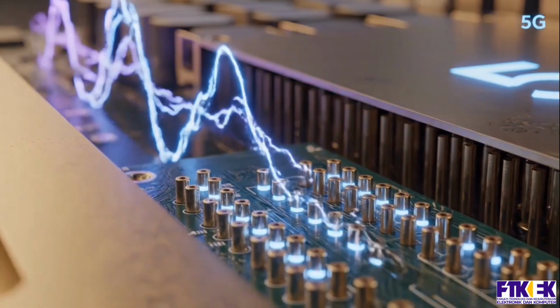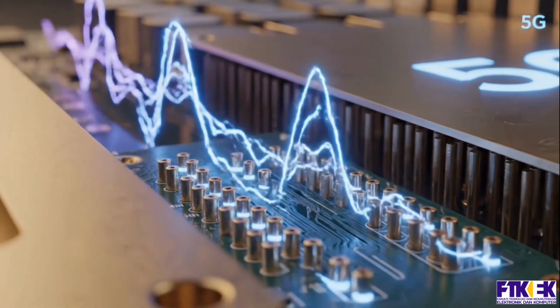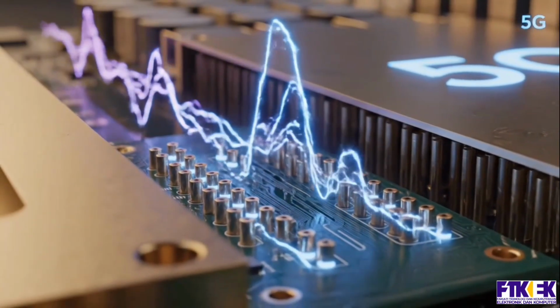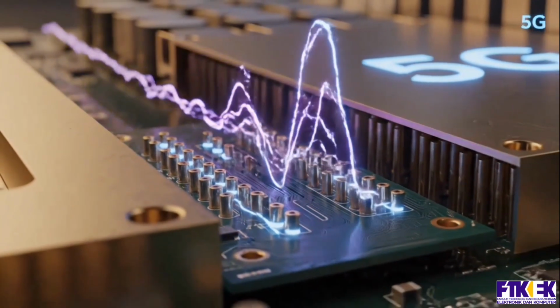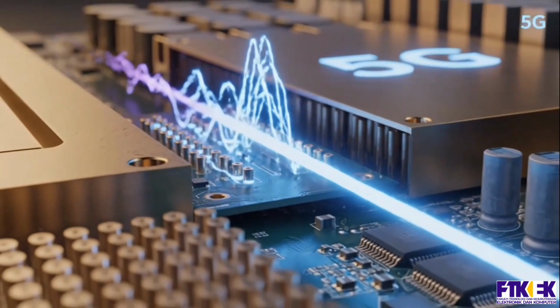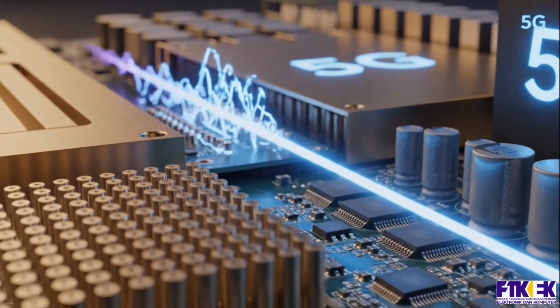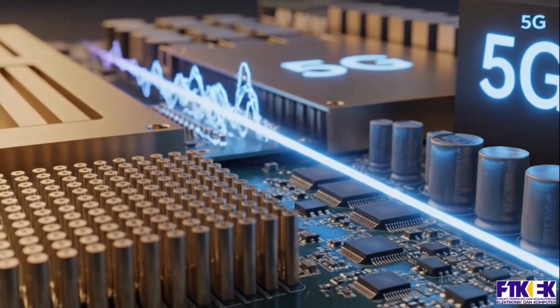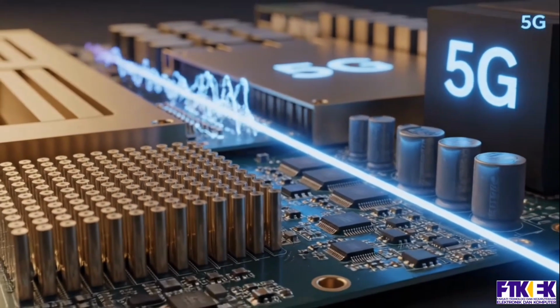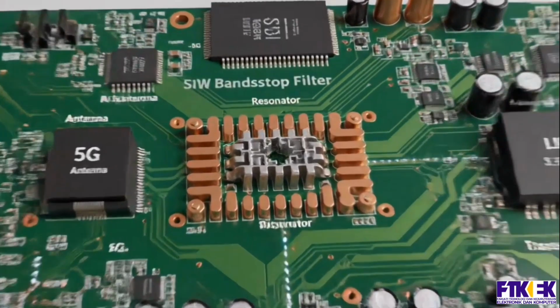Our design criteria were strict. The filter had to be compact, low profile and highly selective. We achieved a total length of 95.33 mm and kept the reflection levels below -15 dB to ensure maximum power efficiency. So the potential applications are vast. The filter is a perfect fit for 5G base stations, specifically for the N78 band used globally.